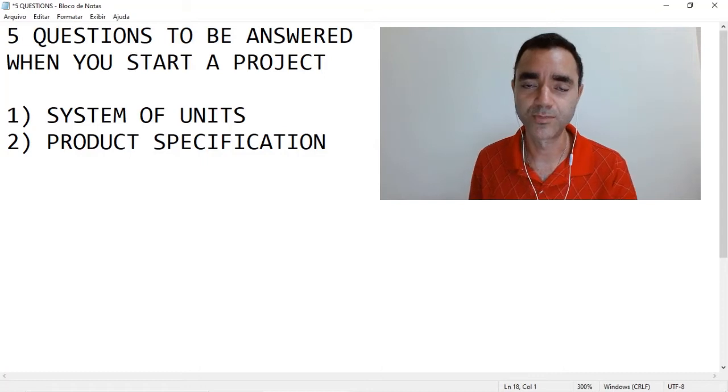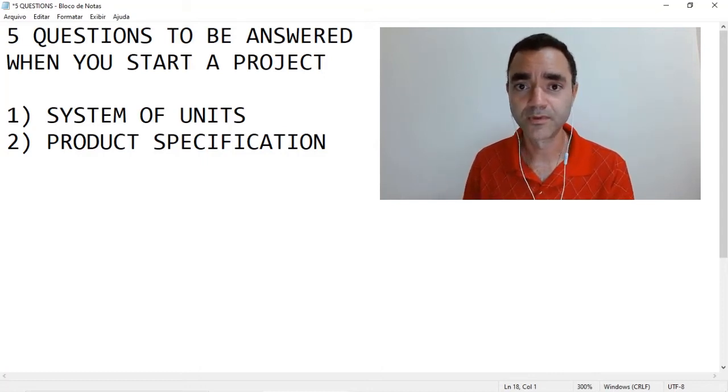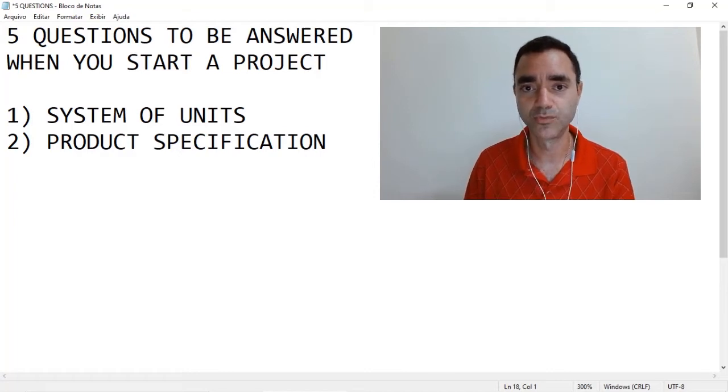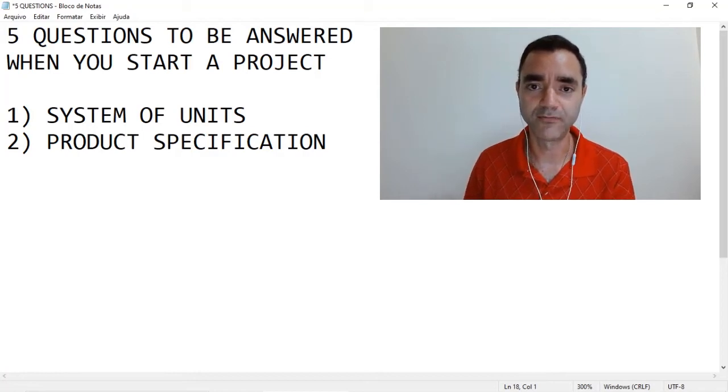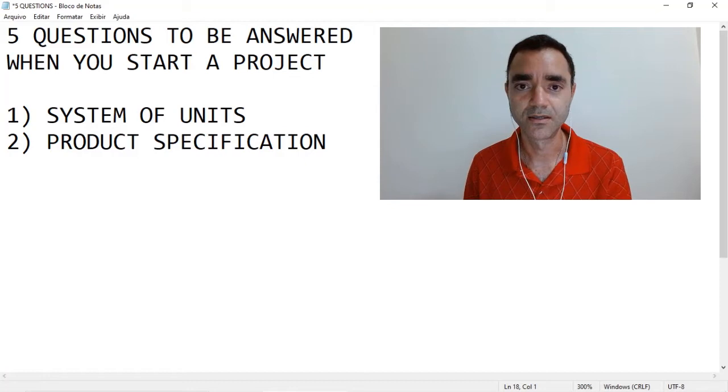And in his technical specification, there was the volume, and based on that, I was able to verify the size of the technology that should be applied to upgrading of the biogas, but I didn't have information related to the biogas composition, the pressure available, the temperature available, how much H2S was in the gas, or how saturated the gas was, if it was saturated or not. Taking this case as an example, let's suppose that I have 100 ppm of H2S in my biogas.